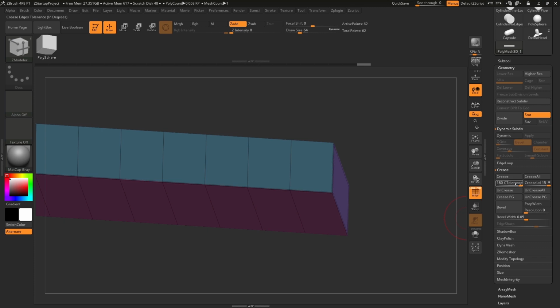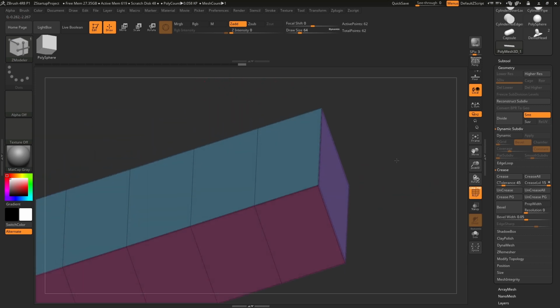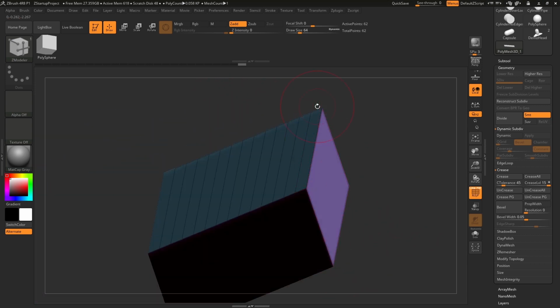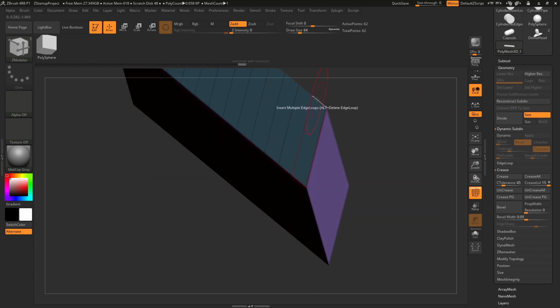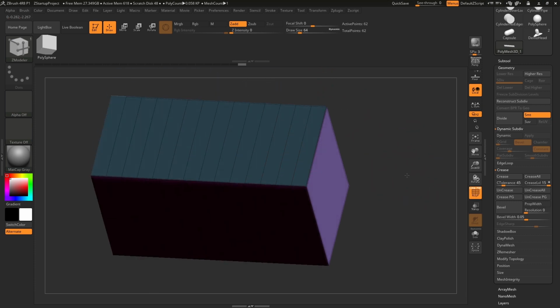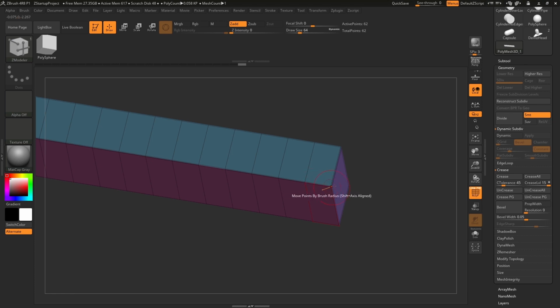Now I can go to the crease tolerance here, and I can change this to something, say, 45 degrees. And this is going to look at all the edge angles on your mesh. And any angles that fall in this tolerance, when I click this crease button, it will apply a crease to those edges. So by setting this to, say, 45 and now clicking crease, you're going to notice I'm now going to get a new crease generated at the top and the bottom of this mesh, since the angle of the surfaces here were falling in that 45 degrees. So these were very harsh angles, so it's going to find these and then apply a crease to those areas. So now I have creasing applied based on those polygroups and then also by this crease tolerance. So now I've just creased my model entirely.